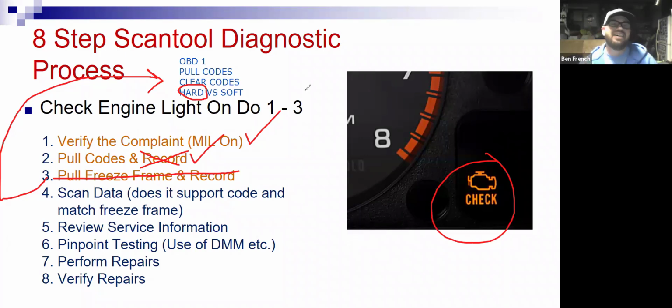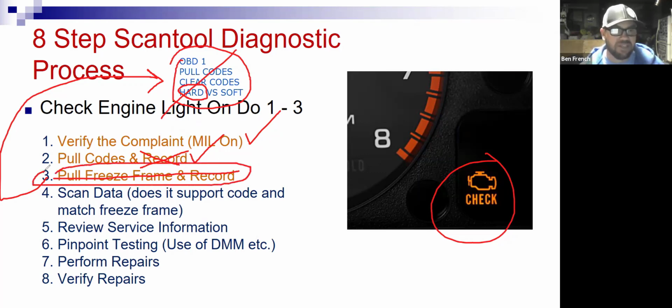Anyways, a lot of people will take this old strategy and apply it to OBD2. And the reason we don't want to do this, so now I'm going to put a circle, cross it out. The reason we don't want to do that on an OBD2 vehicle is when we clear the codes, we lose our freeze frame information.